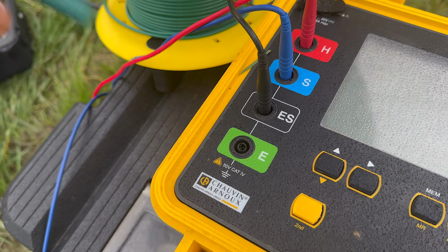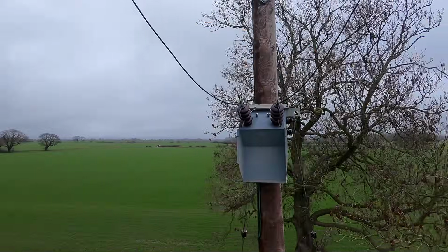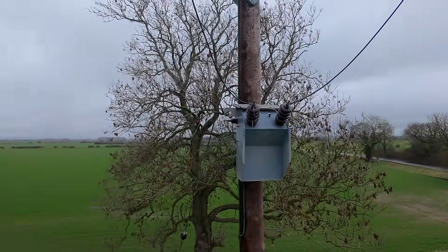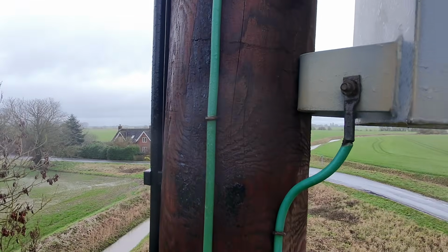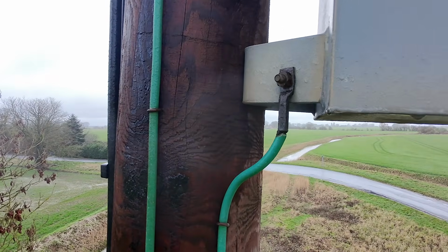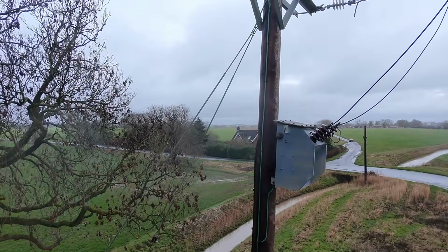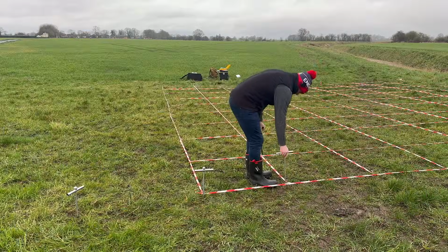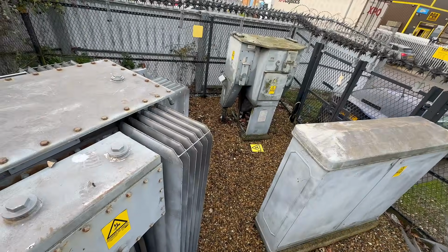And that's exactly why a distribution network operator, or DNO, tests the resistivity of soil before deciding where to put a substation or transformer. The substation and transformer is not just there to step the voltage down, but it's there to be part of the earth fault loop path. If the ground around the substation has high resistivity, that fault return path could be compromised regardless of how well the rest of the installation is designed or installed. By carrying out resistivity testing first, the DNO can make informed decisions about where a substation is best located.